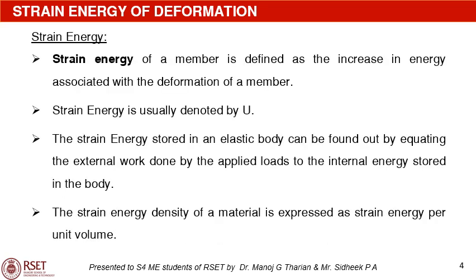Now, we will see what is strain energy. When a body undergoes deformation under the action of externally applied forces, the work done by these forces is stored as strain energy inside the body, which can be recovered when the body is elastic in nature. Thus, strain energy of a member is defined as the increase in energy associated with the deformation of a member. Strain energy is usually denoted by capital letter U.